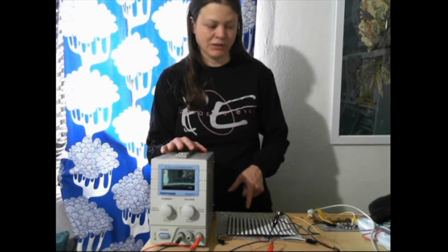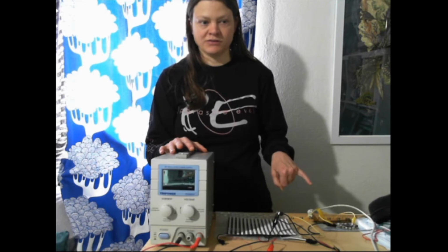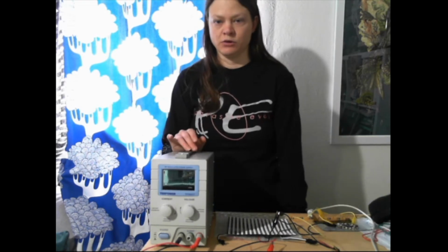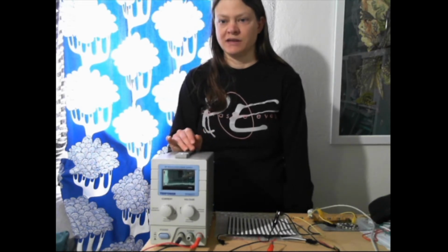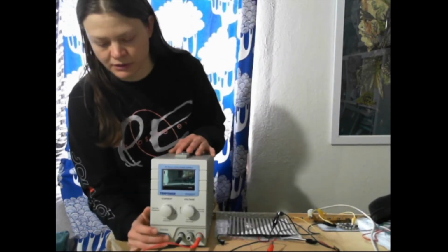If you have too many lights plugged in, like running them off the board without external power, it's very easy to make your Arduino freeze up because it can't power itself. So we're going to turn the power supply on first, turn it on or plug it in.